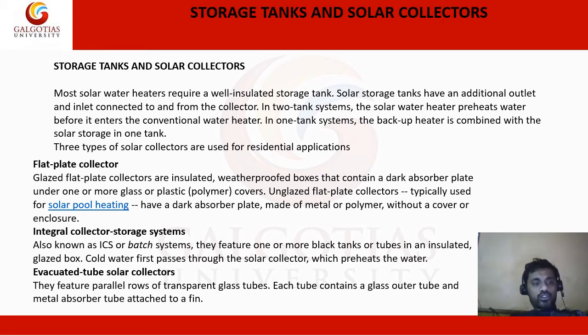So solar water heating systems always require a backup system for cloudy days and times of increased demand. They usually provide backup and may already be part of the solar system package. And since an integral collector storage system already stores hot water in addition to collecting solar heat, it may be packaged with a tankless or demand type water heater for backup.